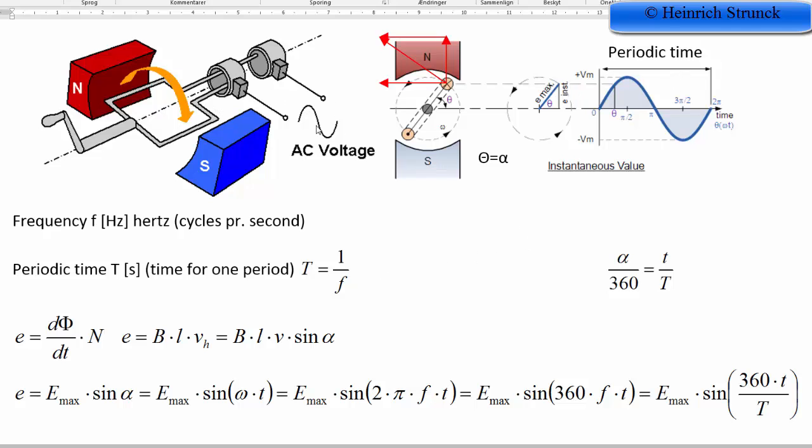So when we generate this voltage, we can see we have a voltage raised to a maximum. It is when the wire is located right here, and when the wire is centered on the south pole, we have rotated 270 degrees, and we are down here, and we have the highest voltage again, but now it's just negative.